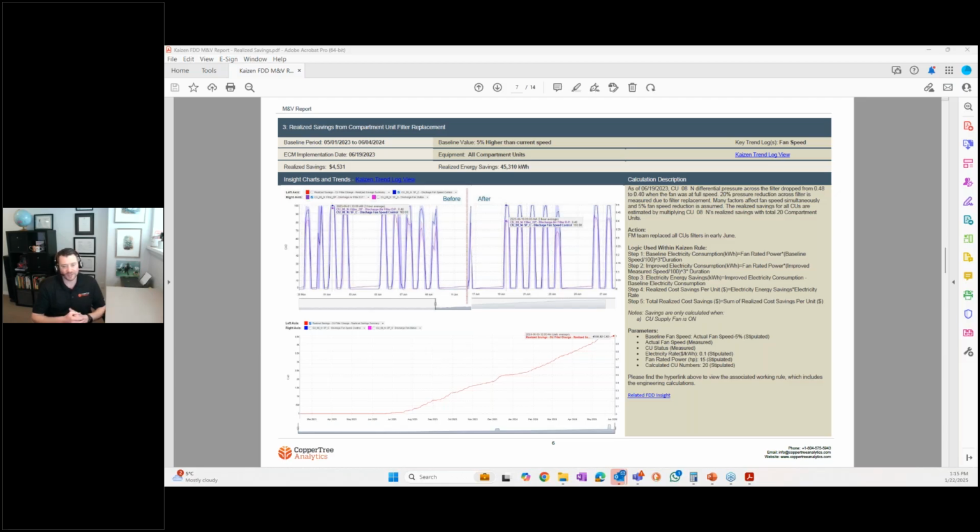We see, for example, an end-of-line unit that's still on the factory program. We forgot, or it got reset somehow, and it's a rogue zone doing whatever. There's stuff like that that naturally gets missed out of those 400 boxes you've had to do. That's where we see the new construction, and it's ACX that would probably find that most. Whereas ASO is really focused on optimizing. And again, we haven't found a lot of interest in optimizing the building as we turn it over pre-substantial, right? That's really not in anyone's best interest, because they want to see how it's going to perform as designed before they go and make changes to it. I think that's pretty common across the projects we see.